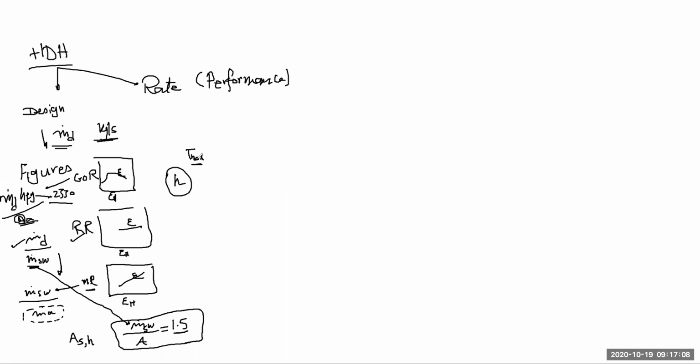So we're talking about some sort of standard steps that you are going to follow in order to do a thermal design of the unit. I can expect, when I'm asking you to come up with a design for an HDH system, that I would have results that are not similar, because there's a human factor when you get a value of the figure. Somebody can calculate the GOR as 1.9, another one calculated as 1.95, 2 or 1.8, something like that is acceptable as a tolerance in the solution.